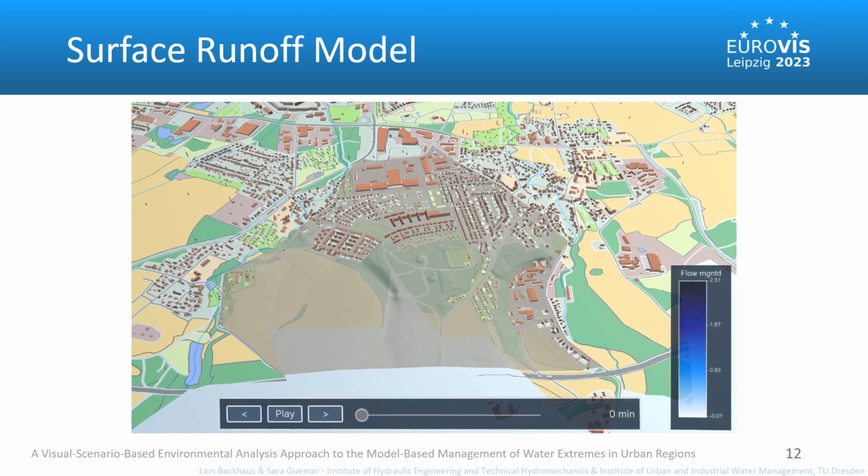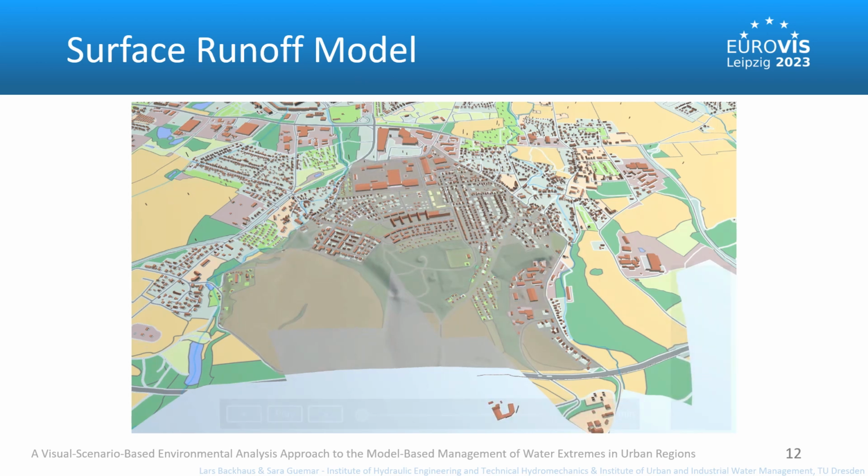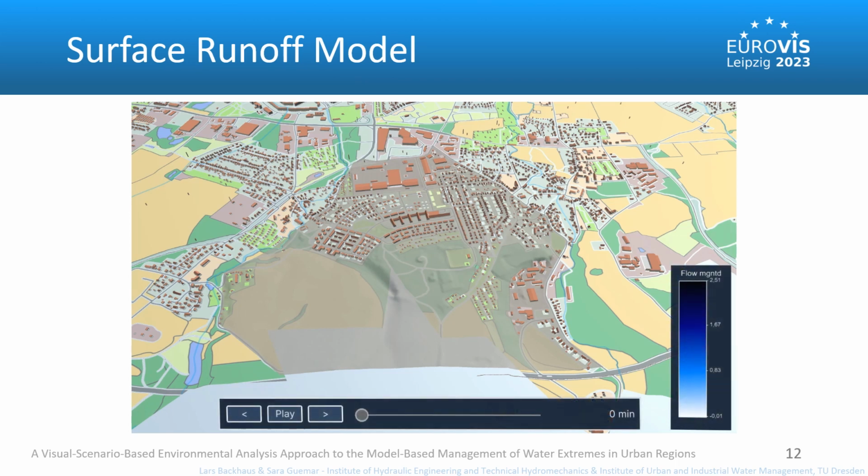The initial stage of the coupled hydraulic simulations is a surface runoff model driven by heavy precipitation events. A computational triangle mesh was created using BASEMENT software tools. The mesh consists of approximately 3 million cells for a total of roughly 35 square kilometers. The base model was refined with additional per cell data such as surface roughness and precipitation runoff transformations, taking infiltration and transpiration into account.